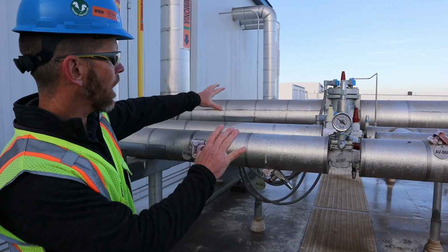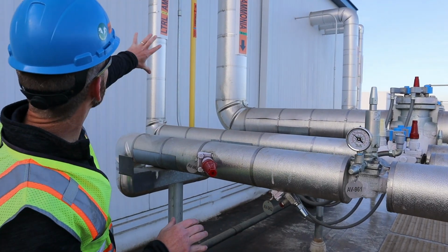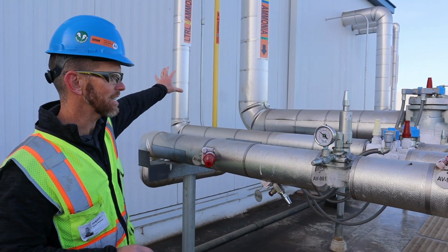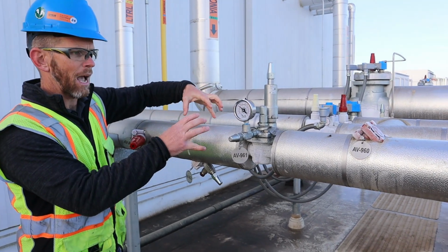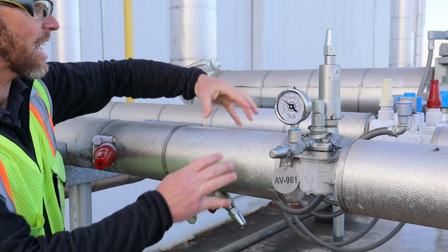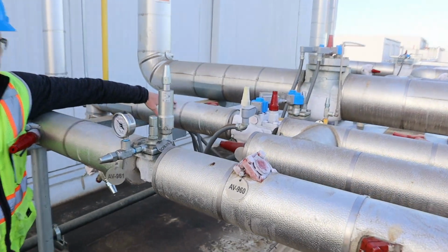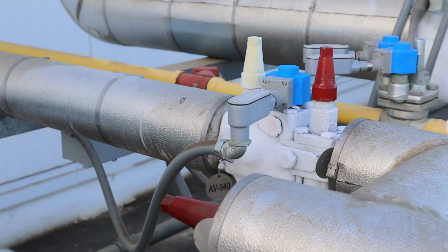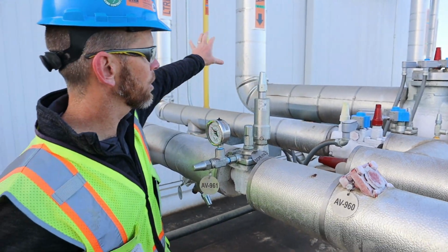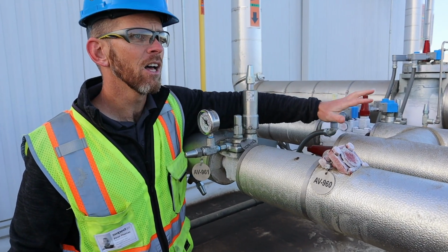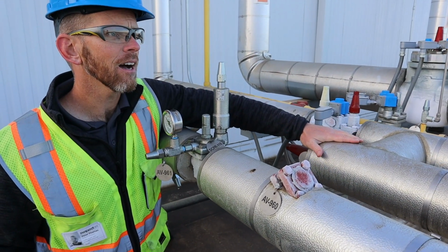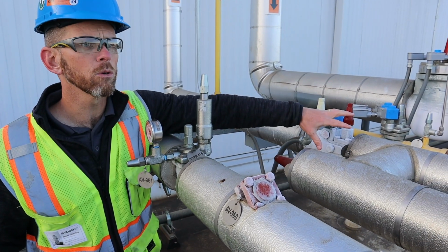First of all, we've got a lot going on here. This is piping going to a single evaporator inside a penthouse, and mainly there are four different pipes. This first one we call the defrost condensate. This is our recirculated liquid. Now this particular evaporator is called a convertible evaporator because it can be connected to the high temperature liquid or the low temperature liquid.